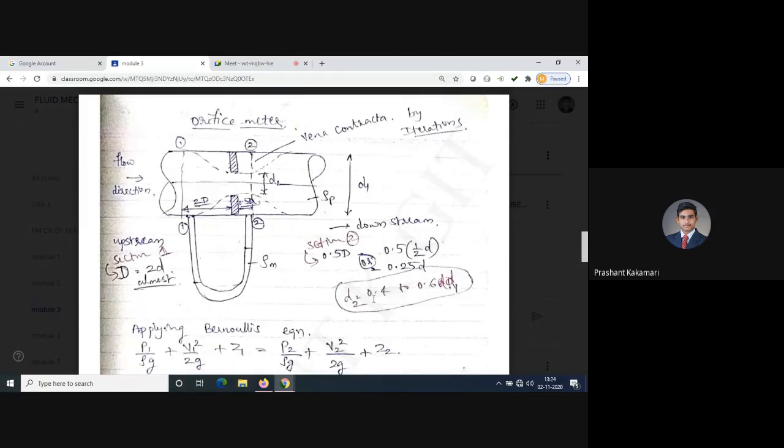And if you see the orifice in the lab, the manometer connections, one tube should be at the inlet side of the pipe. The complete pipe can be connected at section 1, and another tube of the manometer should be connected just after the orifice plate. Why am I calling it the orifice plate? Because in the entire pipe, the only change in the diameter is with respect to this plate, what is shown with the hatches. This will have some very small thickness. The opening of this orifice plate will be exactly at the center, concentric to the pipe itself. And the diameter of the opening can be considered as 50% of the pipe opening.